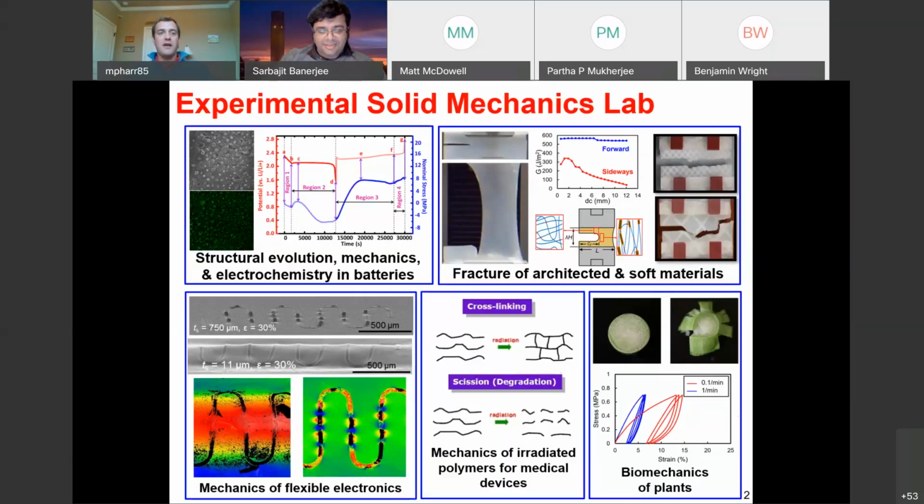And they grow things, different genotypes of plants. For instance, is shown here in this image of sorghum. We test mechanical properties. You can imagine it's a fun composite hierarchical structure, rind, skin, cellular bundles, etc. And it has very time-dependent deformation, sort of poroelastic type mechanics. And we see what genotypes are best for preventing issues of failure in the field when subjected to various environmental conditions like strong winds and things like that. And we also do the opposite, where we grow some sorghum in a greenhouse and have a control group that just sits there with no wind, if you will, and another group that we whack back and forth with big rigs that we build, and we see how that can change genetic traits, so epigenetics, how it can change anatomical features, and also biomechanical properties.